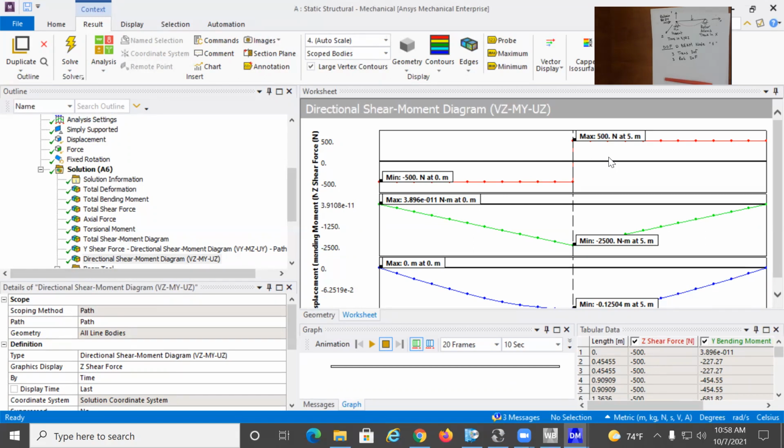If you want to attempt the second problem, you want to make sure to use add frozen and use different types of section for 3 regions. Even though the bearing is not applied to a point, we want to apply the pin support to a point, because the length where the bearing is applied is relatively small compared to the length of the shaft. So it is an acceptable approximation to apply the pin support to a point.